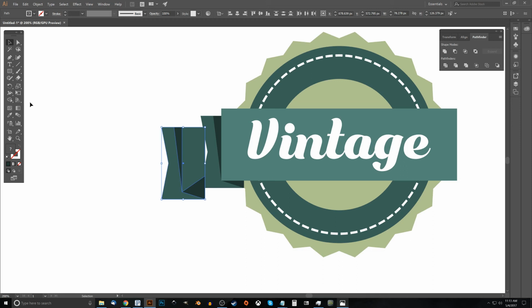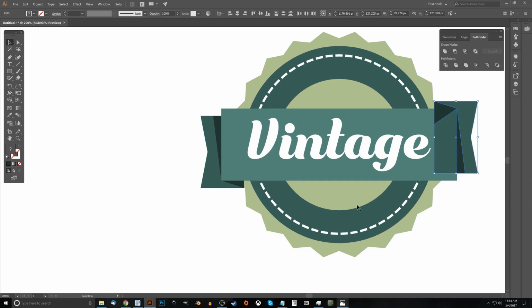And then what I'll do is I'll go to the Rotate tool, and I'll just rotate this around. And once I start rotating it, I'll hold Shift so we could rotate it perfectly according to 45-degree angles. And once we've rotated around 180 degrees like that, we're pretty good. And now we can go to the Select tool. And what I want to do is take this corner right here and snap it onto this corner right here. So in order to do that, I'm going to hold Control on the keyboard, and we're going to get nodes at all of these different little corners. And once we get those, I'm going to grab this object at this node right here while holding Control and just click and drag and snap it onto this corner over here. And then we can let go of everything and it'll snap.